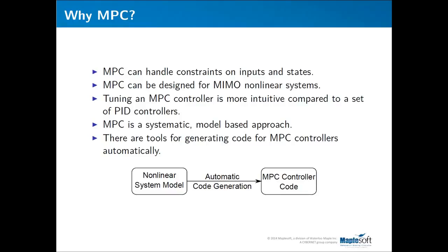Therefore, you can replace a set of PID controllers with just one MPC controller and give it all the measurements that you have, and the MPC controller would compute all the inputs that you need to control the system. MPC is a systematic model-based approach, and what it means is that it's a tool to generate a control algorithm given the model of the nonlinear system and the objective of the control system.